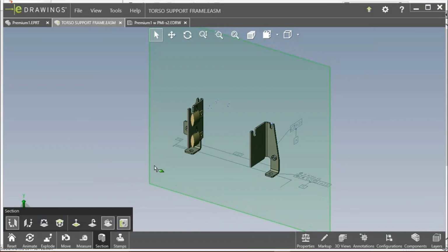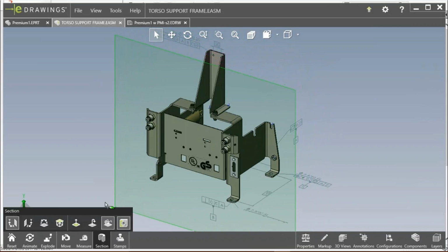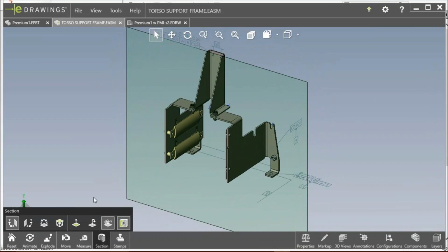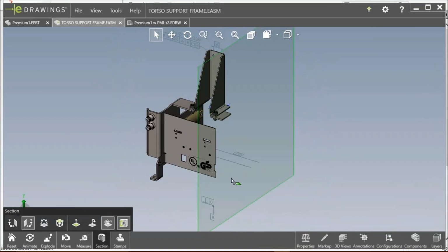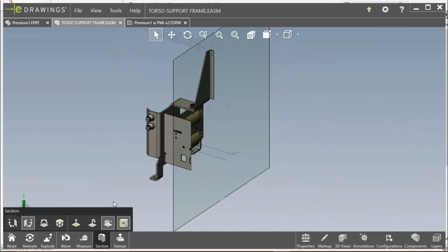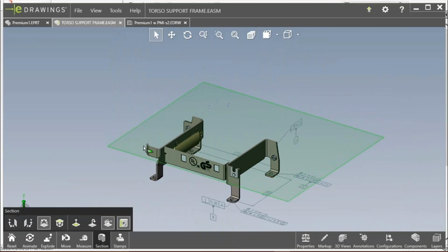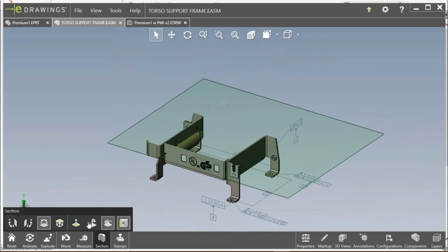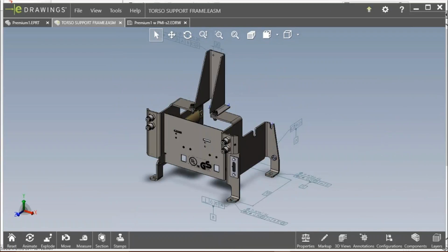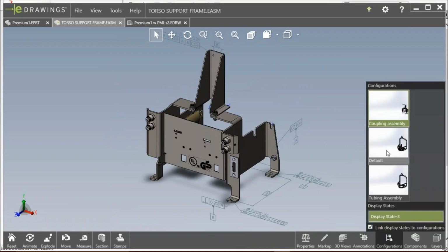And the section tool actually is available at the part level as well. We can get in and section our parts as needed, grab different planes, and see exactly what we may need to see. And we can base this off of faces as well, right? Faces act as planes if we need to. Flip those directions around to get exactly the information that we want.